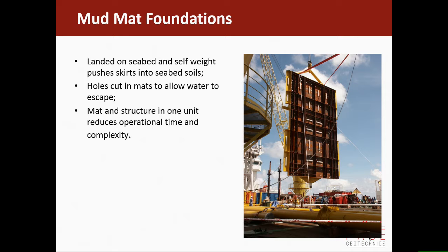If it's a really soft mud, would that extrude up through the dewatering holes? You make the holes about 10-15% of the area. Usually they're about 100-150 millimetre diameter on a sort of half metre or more spacing. If you did put many holes in, then yes, there is that potential. But does it really happen? Not really, you know. I've never seen it happen.